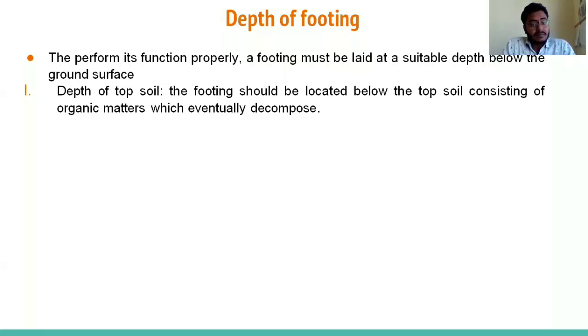Those factors are, first one, the depth of footing, frost depth, zone of soil volume change, adjacent footing and property line, sloping ground, water table, scour depth, underground defects, root holes. So these are all the factors.